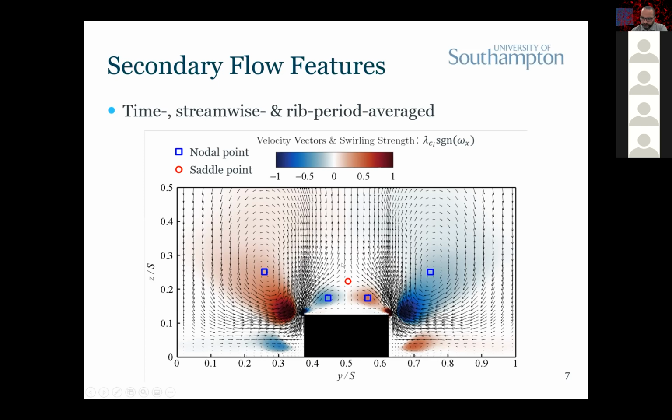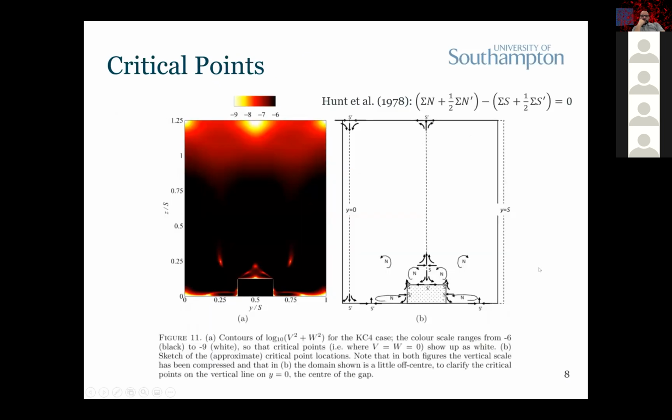If you look at this, because I first commented about this upward moving velocity component also found in Huang and Lee's DNS, now if you look closely, there is a saddle point, and velocity is actually coming down towards the rib, very close to the rib area, due to these rotational secondary flows generated around the top of the rib areas. So these are the things that weren't made clear in the past.